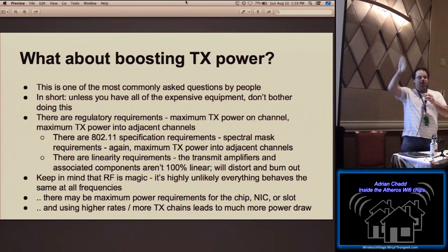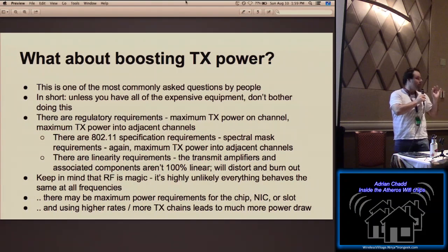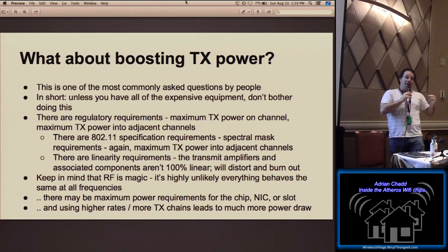It does this, or it does this, or it's wavy. And so as part of the card calibration, they'll actually pick the maximum transmit power that you can do per channel based on what the actual card, when you test it, gives you distortion-wise. They'll say anything more than this much power at this frequency drives the transmitters into some kind of nonlinear behavior. They have to drop the transmit power.